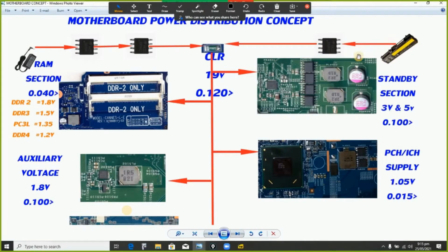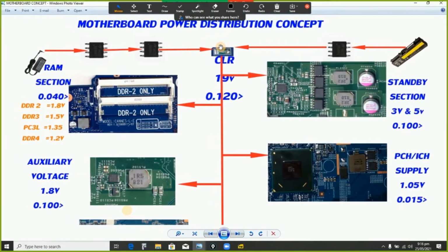Here, let me drop this. If you have an issue where they say water damage and the board is not working, the most common cause is that whenever there is water damage, there is usually no charger there, but there is always a battery there, and because there is power on this battery, it will automatically damage the system. If you did not give any power and the water gets away or dries or any which way, 100% your board will work. So what we are trying to figure out here is, without a source, the laptop will not work.